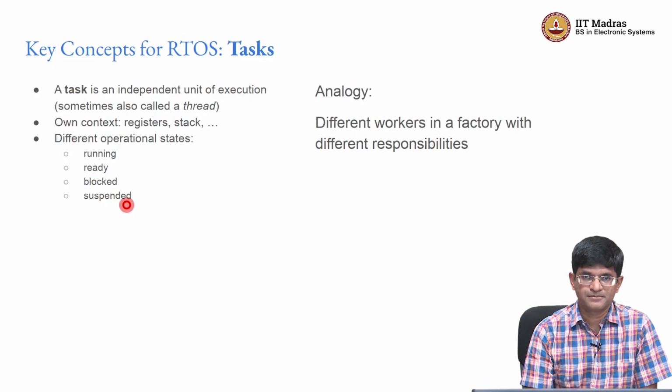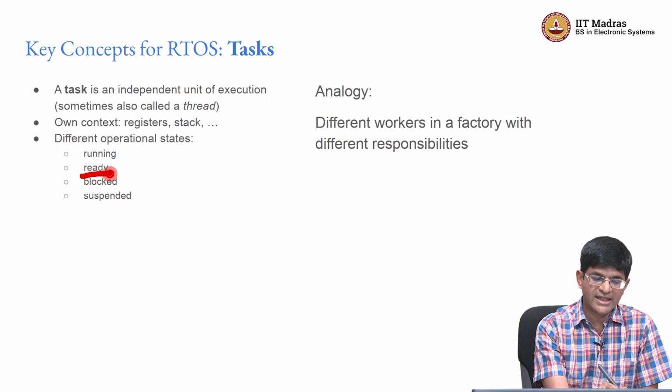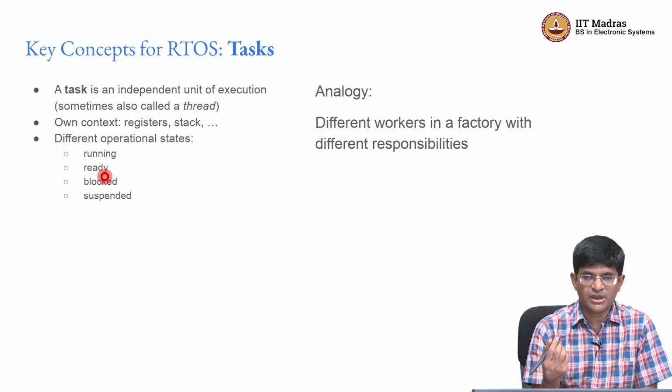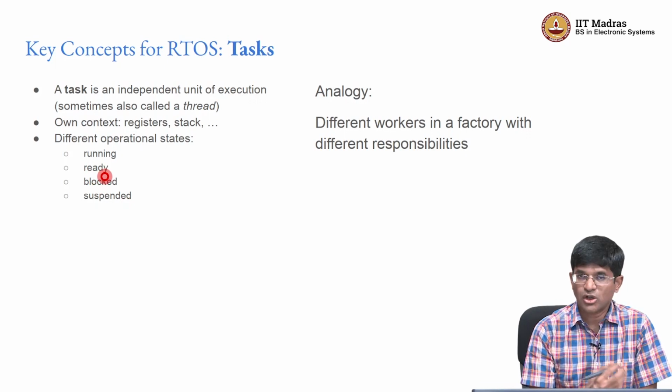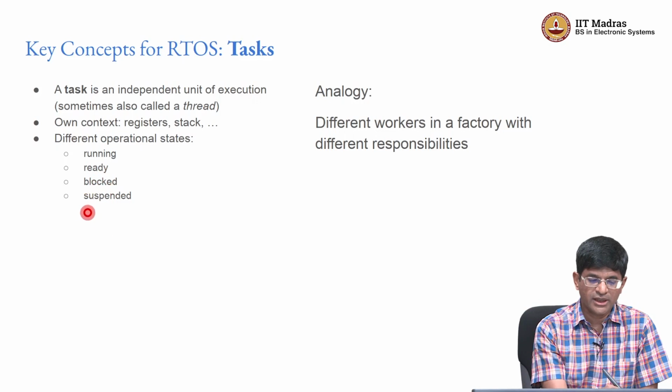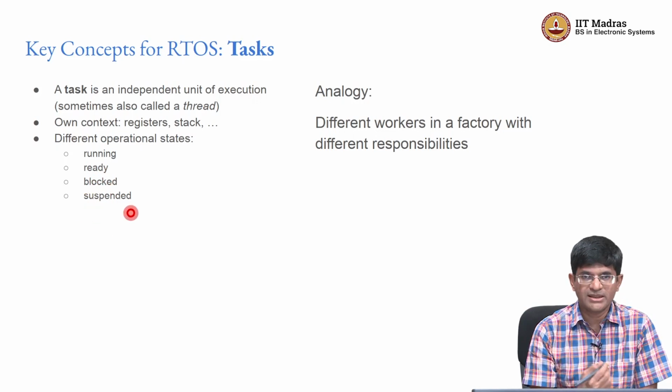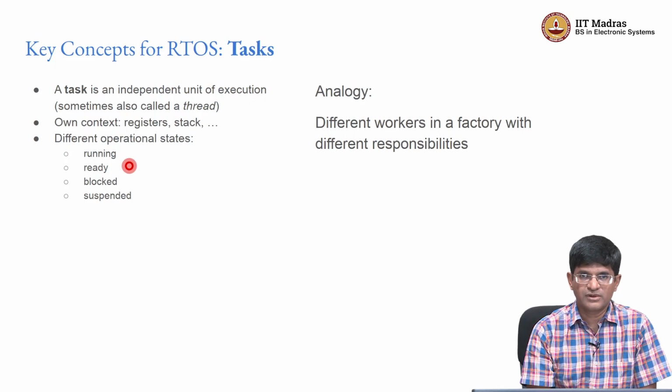So a task could be in a ready state where basically it's not doing any work, it's just waiting for something else to happen. In the context of what we have discussed earlier, it might be waiting for an event to wake it up and tell it what to do. It could be blocked, waiting for input. It could be suspended, which could be something directly done by the operating system, which basically just puts it to sleep for a while so that it's not active at the moment. There are other possible states, and this is not an exhaustive list of possible states.